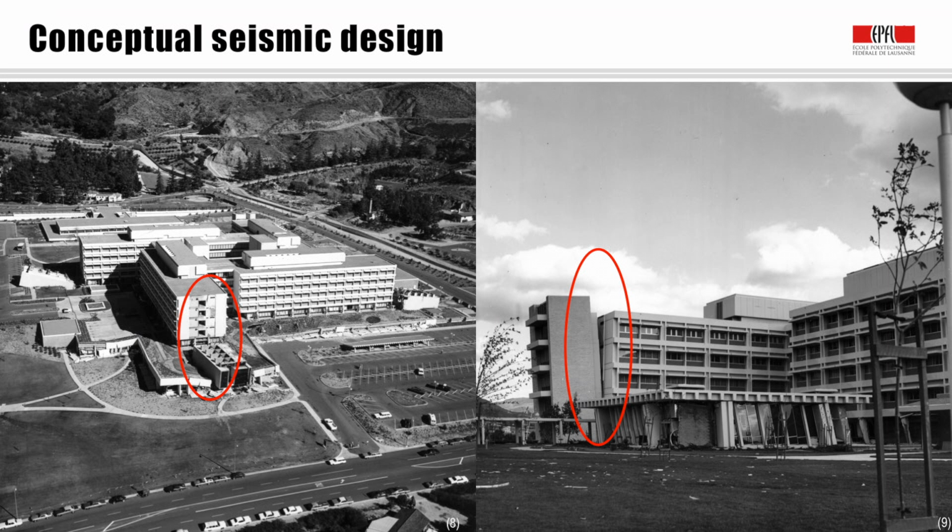Also, the slabs that connected the frames to the walls had not been designed to transfer these forces, and they broke too, as you can see here on the right, for the one staircase that actually remained standing up. So if you combine 2 structural systems in one building, it is important to remember that you need to design the stiffer structural element to take forces from the more flexible one, and you also need to design the slabs to transfer these forces.